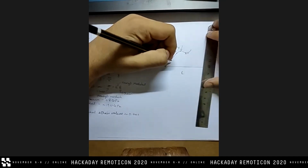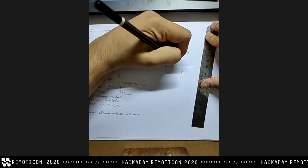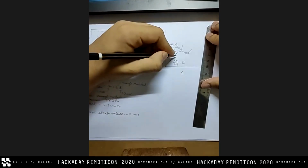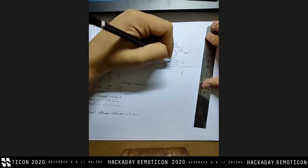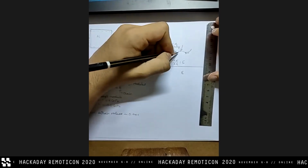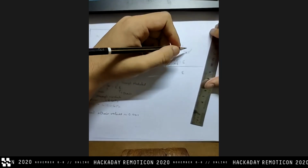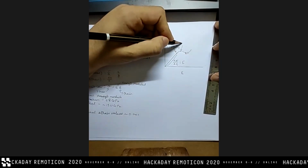So over here, if you look at your gradient, your gradient is equal to Young's modulus, and that is only true for this region. Because as you can see over here, you no longer have that constant gradient. If you want to be a bit more technical, at later points you actually have a variable Young's modulus, but that's something you don't really have to worry about. But yeah, that is something interesting.